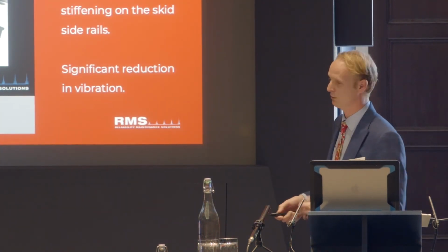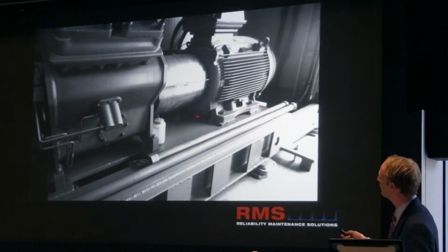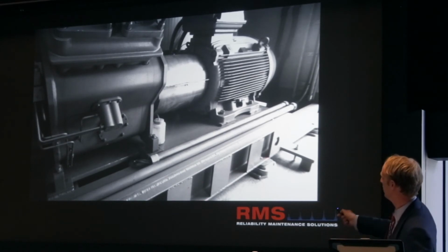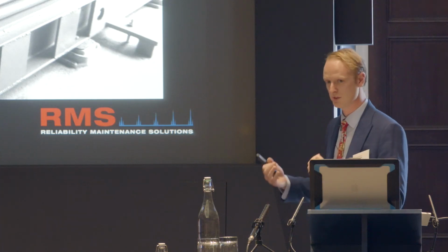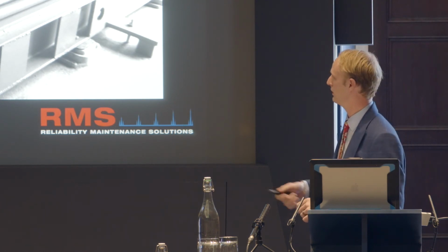So the solution, we gave the data over, and the solution they came up with was to add mass and stiffness using a very thick piece of steel under the bed. This is running next to the one I've just shown you. And they've added stiffness along the base, which has massively reduced the noise. It's massively reduced the noise.